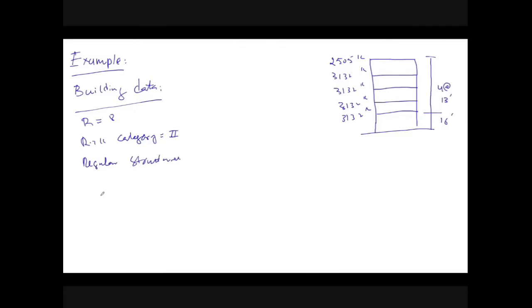The site location of this structure is given because if you are designing this as per the IBC, it's important to know where this structure is located. The total weight of the structure is equal to 15033 kip, if you sum the floor masses. And the modal period for mode 1 obtained from the computer program is 1.45 seconds.